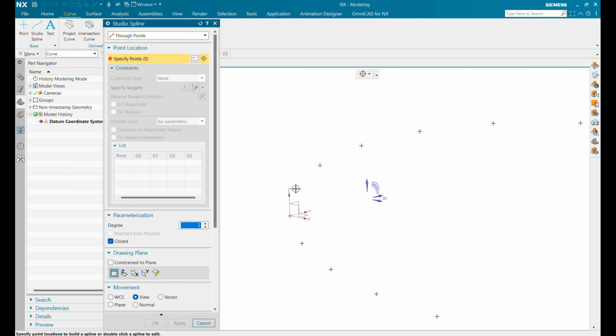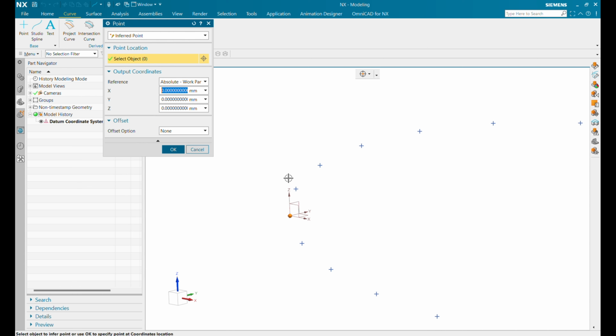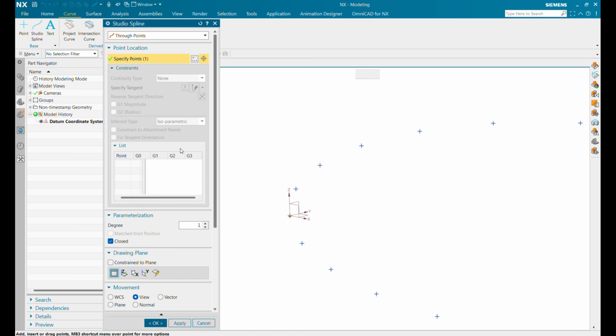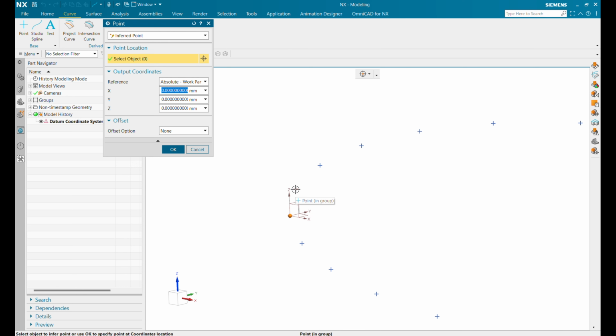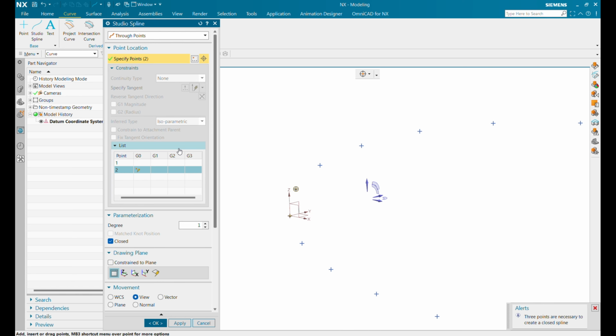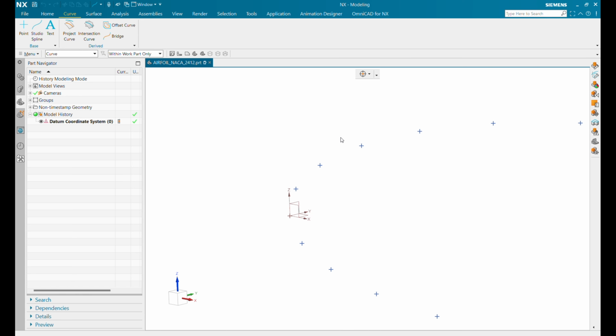However, you will notice that this is an extremely tedious and slow process, as you have to select every point after multiple clicks. So for example, I click this point, and then I click add new point, select the point selector button, select the point, click OK, and then repeat the process.